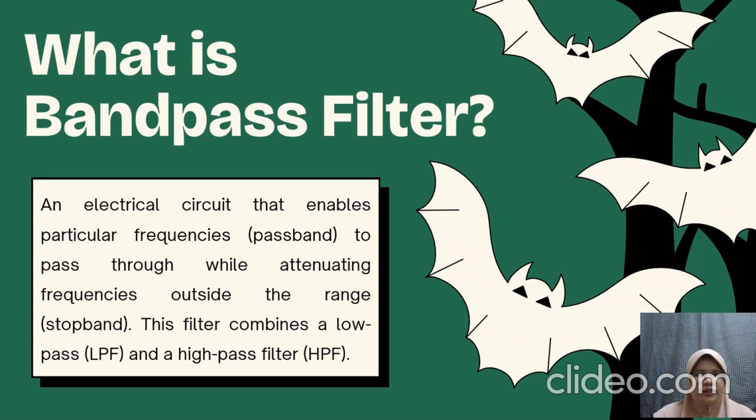So, applications of filters. Tuner in radio, which uses a bandpass filter that allows a fixed frequency to the speaker. Noise separation, which is used for noise removal from the received signal. Anti-aliasing, which uses a low pass filter to filter out high frequency components to prevent aliasing components from being sampled. Treble and bass of a speaker, which use low frequency for bass and high frequency for treble. They are separated and routed using high and low pass filters to produce clear music.